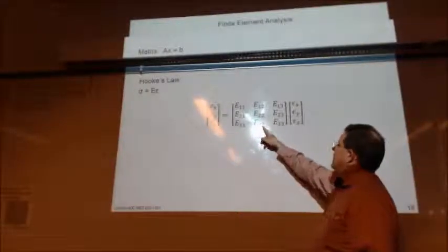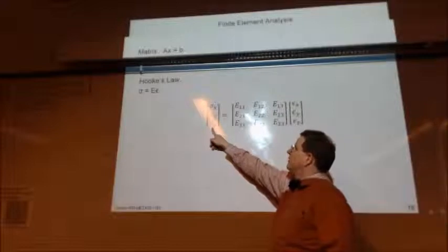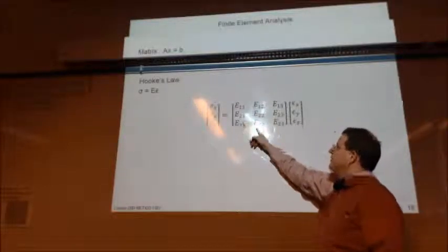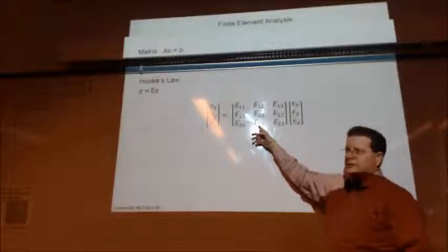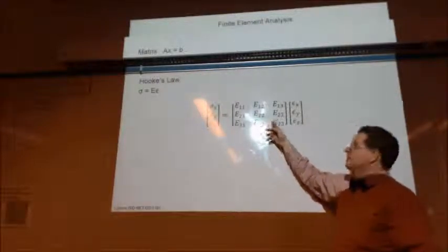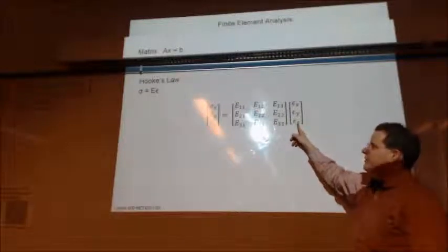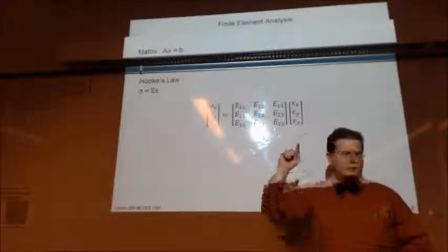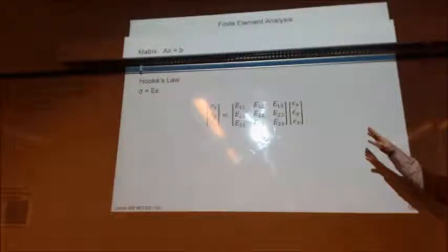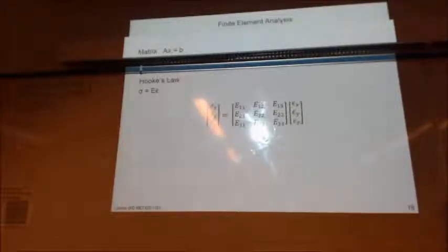So this is our A, our X, and our B. So we have our stress in 3 axes, we have our E in 3 axes, for say steel, that should be isotropic and homogeneous, right? And then whatever strain is happening in those various directions. Okay, and then you're going to do the matrix multiplication to determine what your stresses are.